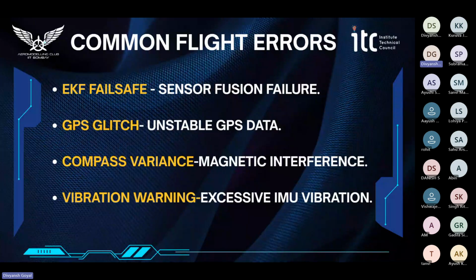And there can be vibration. See, vibration is the biggest enemy of a drone. We have to check whether our propellers are loose or there is a loose connection between our wires, because excessive vibration can cause failure.